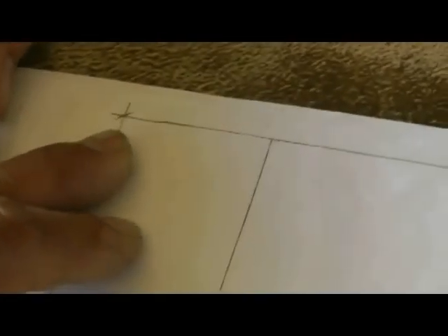Once you have those established, also just to make a general note, we want to be 5 feet minimum from the property lines. In other words, here's the property line, here where my finger is. So we want to start the building right about here, 5 feet. And when I drew these plans, I didn't have these exact property measurements. So I was just kind of going on the fly, but now that I have them, those numbers can be established in this instruction video, okay?